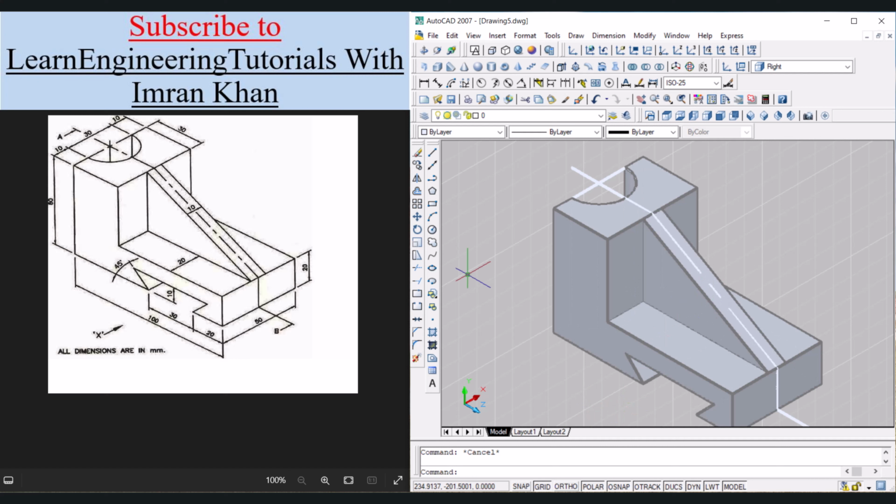But the scaling is not okay. So for that, write LT, enter. Let the scale be 0.5, and we can see that this is the same scale used by this diagram, right?